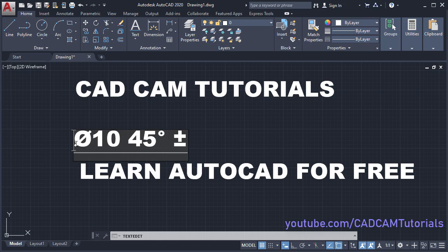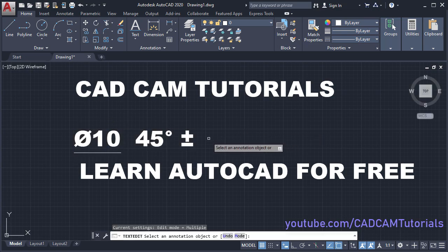And if you want to underline particular portion, suppose I want to underline dia 10, then take your cursor after 0, click there and again type %%U. So only that portion will get underlined. So in this way you can add special symbols. Click outside.